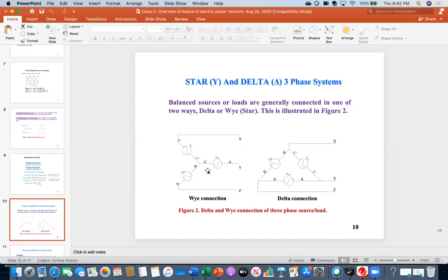Even though the neutral line can be grounded, for example, you are somewhere barefooted and you are working somewhat nearby that grounding place, and you are not aware of any unbalance in this case. What will happen? You suddenly get a shock, and you don't know from where that current is coming, assuming that the soil or the land is wet, or it's a rainy day and you were barefooted nearby the grounding. Do you understand?